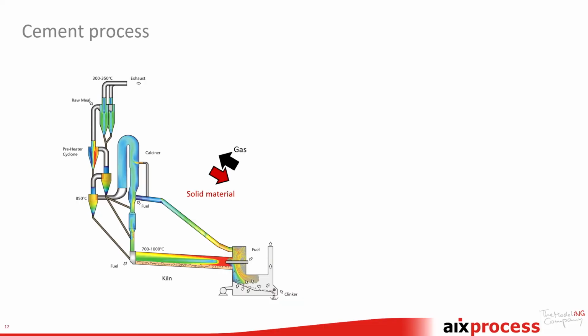To give you an idea about the cement process, it's a counter-current process. The solid material moves from up left to down right. This is the entry of the so-called raw meal. It is injected to the cyclones, which we call the preheater tower. Then it's calcined in the so-called calciner. It enters the rotary kiln, and then it's cooled and ejected as clinker. The gas flow is countercurrent, so you use the cooler to preheat the gas flow. You have fuel into the kiln combustor, and this is the so-called tertiary air duct, and then you go towards the calciner and then separate the meal again.